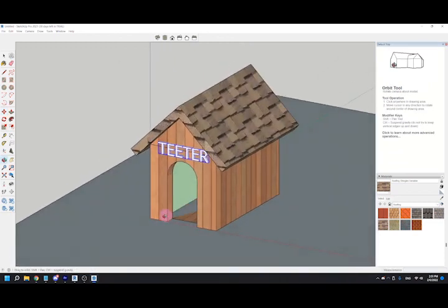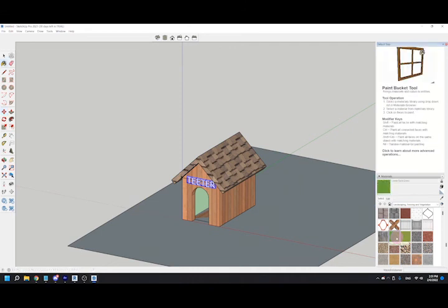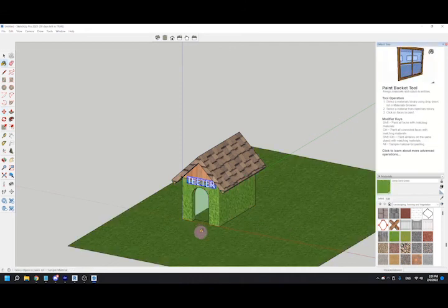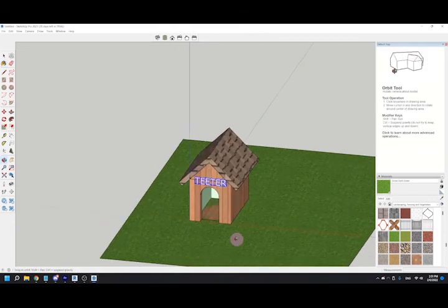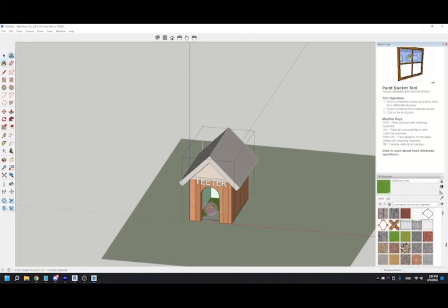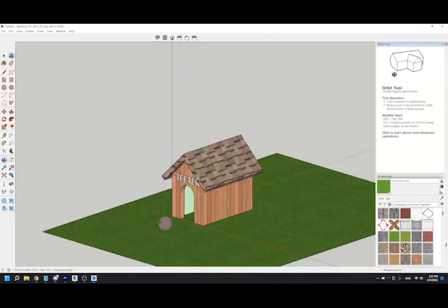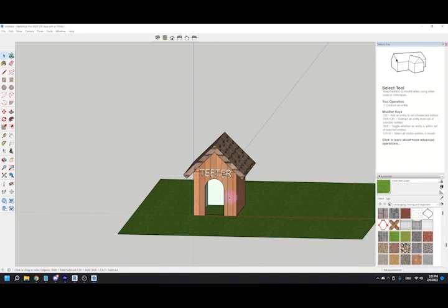And then we'll put it there, and we'll add in our material for our ground too, so that'll be in landscaping. We'll pick out a nice lush grass. Whoops, Control Z to undo that. Then I'll have to double click on this component so that way I could fill in just the ground with grass. So what's happening here, these two different planes or these two different faces are at the exact same spot, and so they're kind of competing for attention almost. And that's why it was clipping, but since I now have them as the same material, they're not really competing for anything anymore.